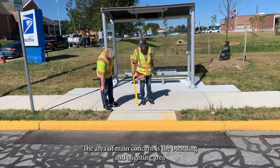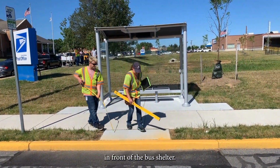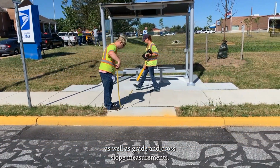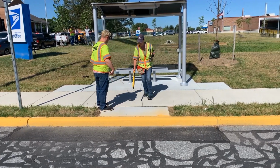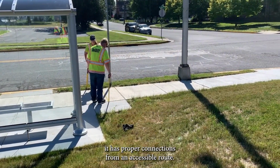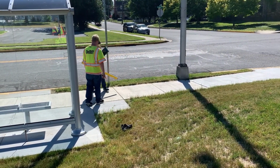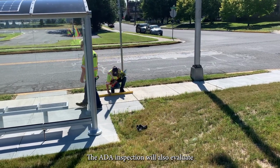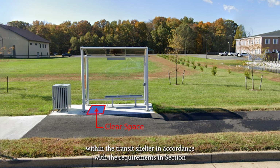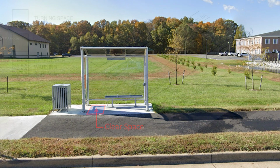The area of main concern is the boarding and alighting area in front of the bus shelter. Required measurements include length and width, as well as grade and cross-slope measurements. The boarding and alighting area will also be checked to verify it has proper connections from an accessible route. The ADA inspection will also evaluate transit shelters to ensure that a 30-inch by 48-inch clear space is included within the transit shelter in accordance with the requirements in Section 3.10.2 of the DelDOT PASS Manual.